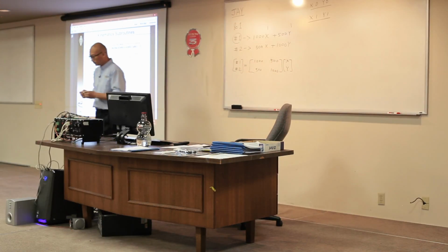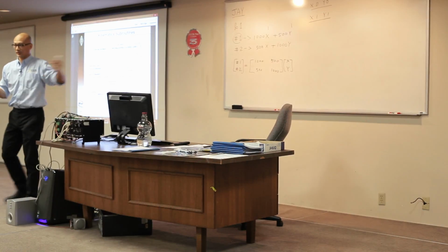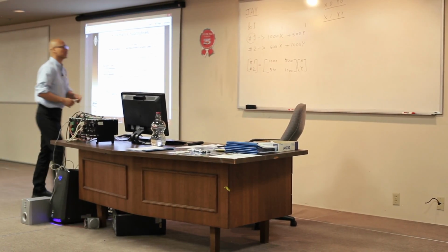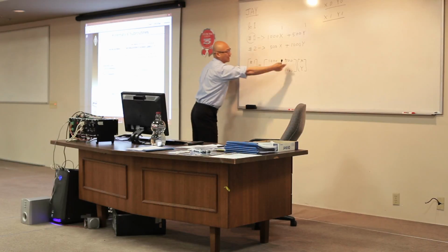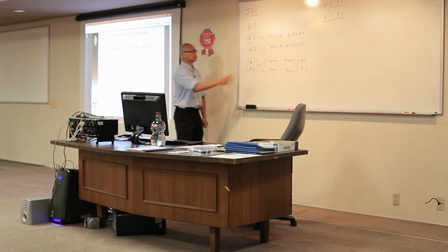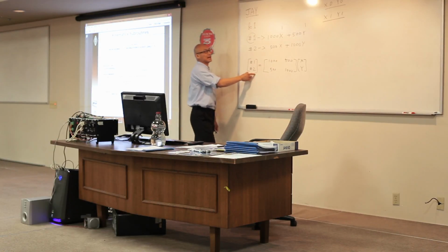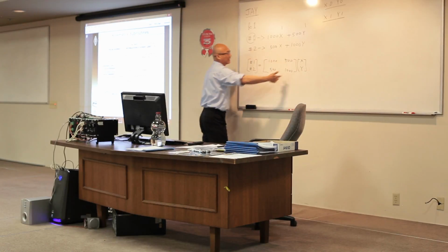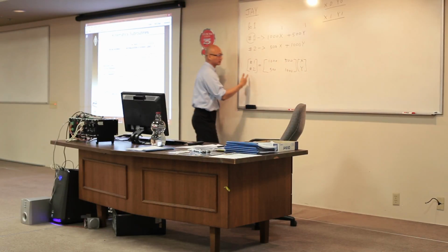Okay? This is a relationship, a linear relationship. So this matrix has to be invertible. So I can actually, from my motor position, calculate the axis position, and vice versa, I use the axis position to calculate the motor position.